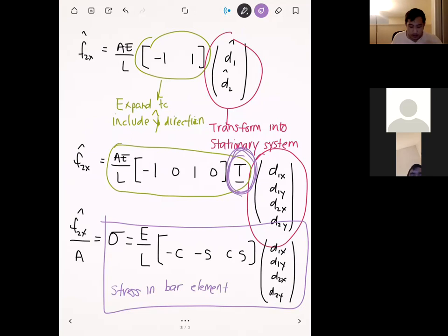And so basically, in order to compute the stress, this is something that you would do after you solve for the finite element solution, and you just have to plug it into this formula here. So you take the displacements that you solved for that element, and you multiply it by its Young's modulus divided by its length, and then you multiply that by this vector, which depends on the element's orientation. I'll do a couple examples with this just so you can see how that is.